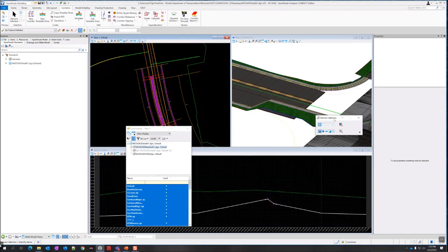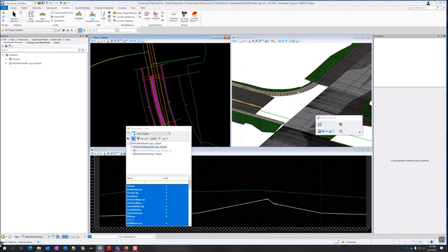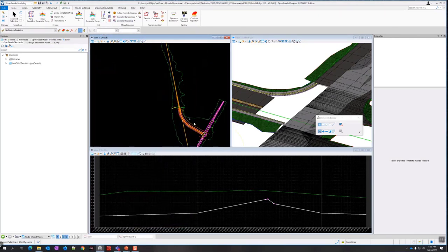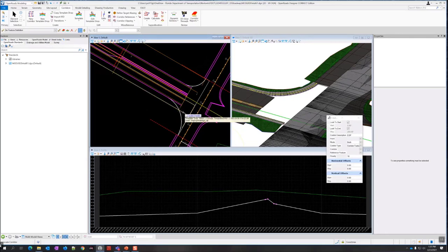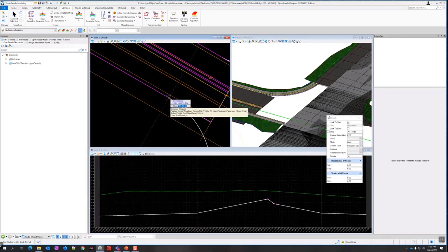Make sure the mainline one is a higher priority. So that's working okay. Looks about right. Now let's do the same thing for the left side. So I'm going to go over here to the edits drop down. I think I don't need level display anymore here. Create point control. I'm going to select this SR61L corridor. I'll go ahead and leave it locked to start, but I don't want to lock to the end. I need to snap to this point right here, 701 plus 34.